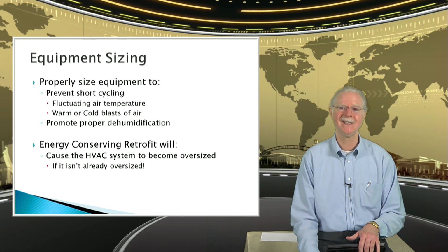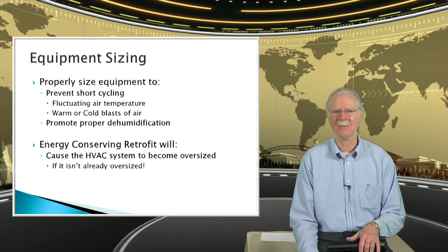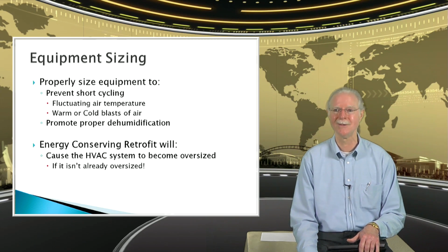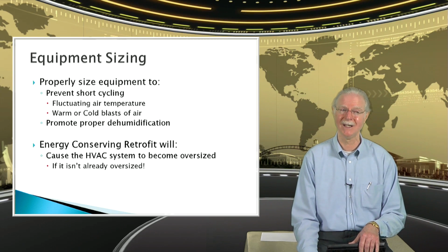The last thing that it does is, if I'm dealing with cooling, I also want it to do dehumidification. In almost every case, if I need to cool, I also want to wring some moisture out of the air. How much dehumidification will I get if I cool down in 2 or 3 minutes and then turn off the unit for an hour or two? Not much cooling takes place, not much dehumidification. The best dehumidification is if it runs 24 hours a day, every day. You can really bring a lot of moisture out of the interior air. So now we end up with elevated interior humidities.